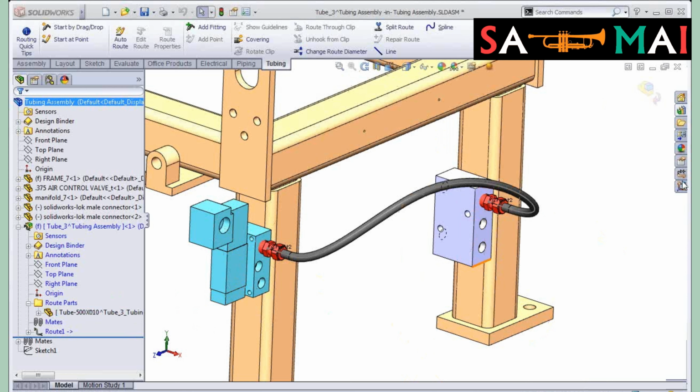You can also, since it is a subassembly, make a drawing and make a bill of materials, and the length will be in the bill of materials, for sure. Or I guess, actually, as of 2012, you don't even need to make a drawing to make a bill of materials. You can make a bill of materials right here on the assembly without having a drawing. But yeah, if you're just trying to check and see real quick, looking in the tree is the best way, in the part over there. I think that's the question you were asking. If not, type it in there again, and I'll look at it at the end.